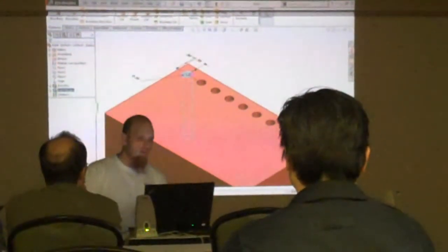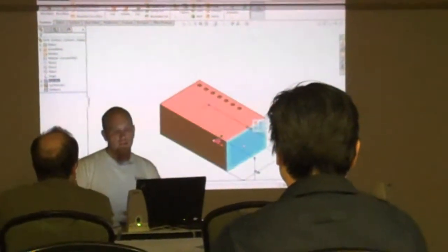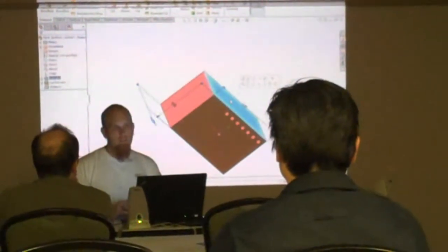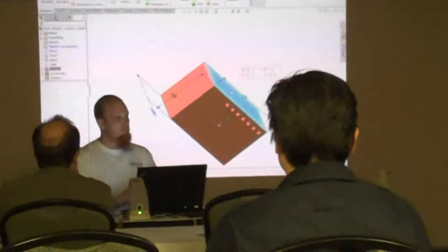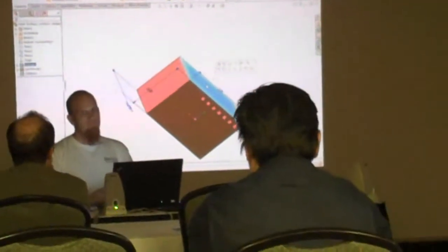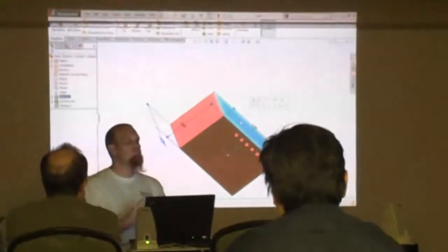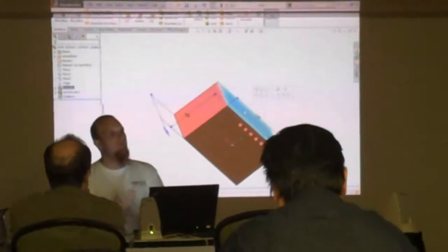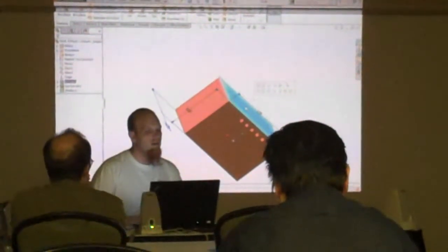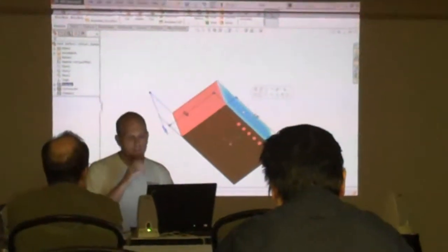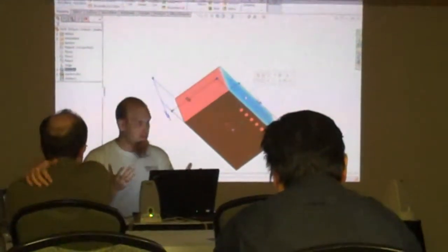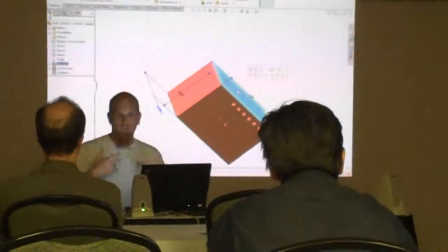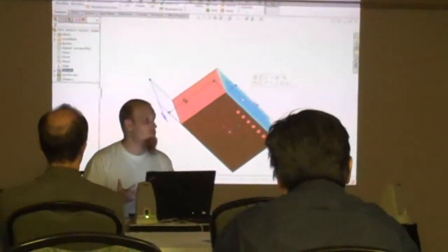I need it over here, and I need one down over on this face. I can either start a sketch, draw a circle, make it 1/4-inch, do whatever I need to do with it, go to the next face, draw a circle, make it 1/4-inch, XY, and cut, extrude, or whatever I need with it. The real design intent is that I'm using probably the same bolt or pin or shaft or whatever to go in each one of those 1/4-inch holes.